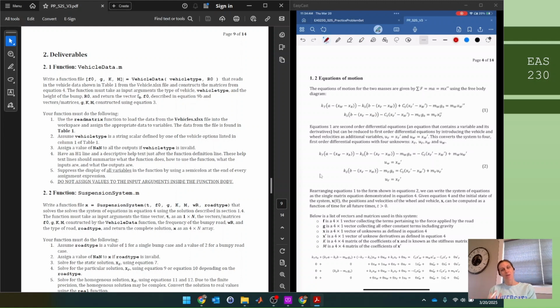However, in order to model the damper, it is the damper constant, so c times the velocity, which equals the derivative of the position, or cx prime. Okay, so that's where these primes come into play. And note, acceleration is the second derivative of position, so that's where the acceleration comes in. But it's really F equals ma, based on that free body diagram. That's really what it comes down to.